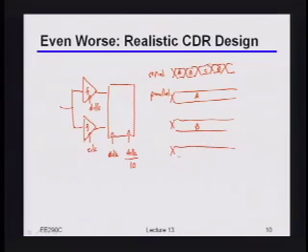I have that C for some period of time, D, and so on and so forth. So what I'm basically doing is taking this high-speed serial data, and instead of having, let's say, 12 gigabits per second on one wire, I could have 1 gigabit per second on 12 wires each. So obviously the net throughput is the same. It's just that now I'm translating it to a lower individual sample rate, but with more parallel wires.